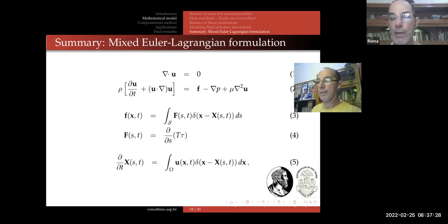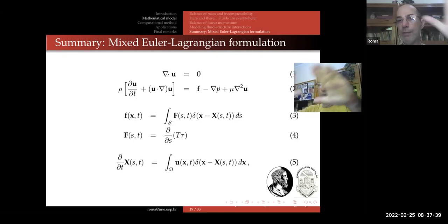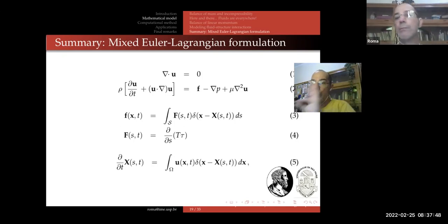So this is the fluid velocity, and I use here the delta formulation to perform something that you can call interpolation. So I have the fluid around the structure points, and I have to interpolate this fluid velocity to the immersed structure points. So this is the complete model: how the structure moves, how it applies forces to the fluid. This is called the immersed boundary model.